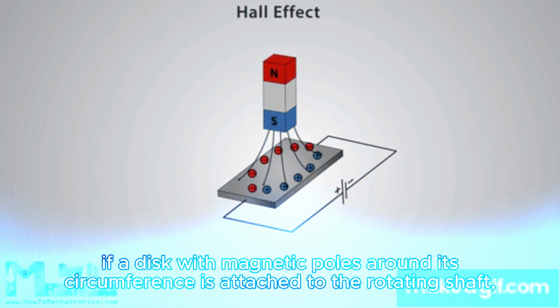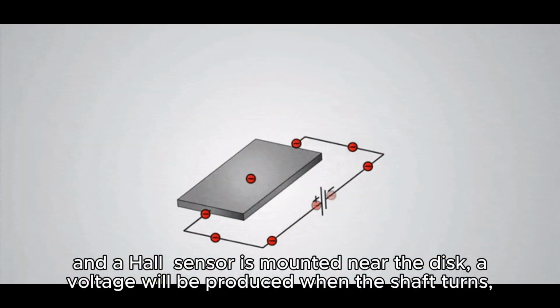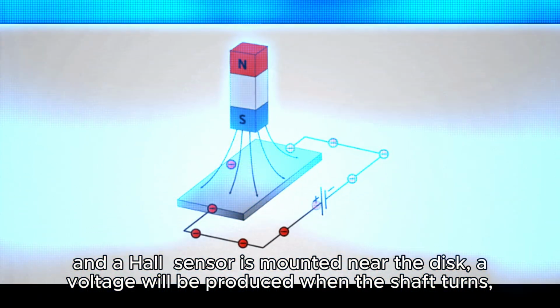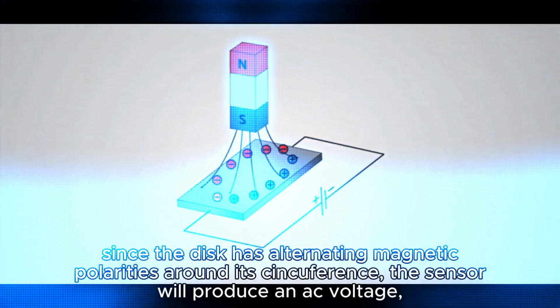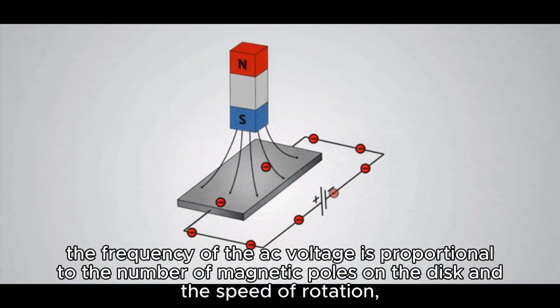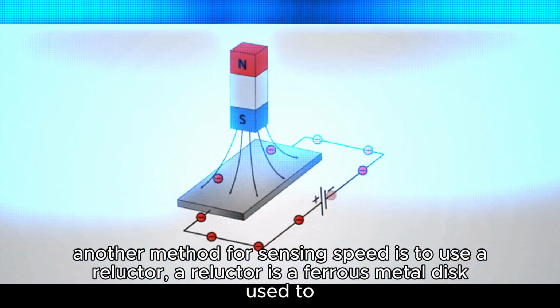If a disc with magnetic poles around its circumference is attached to the rotating shaft, and a Hall sensor is mounted near the disc, a voltage will be produced when the shaft turns. Since the disc has alternating magnetic polarities around its circumference, the sensor will produce an AC voltage. The frequency of the AC voltage is proportional to the number of magnetic poles on the disc and the speed of rotation.